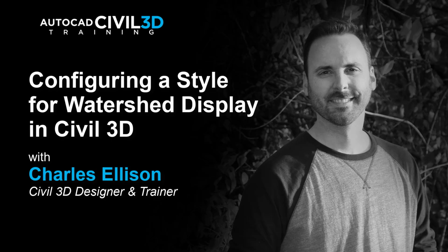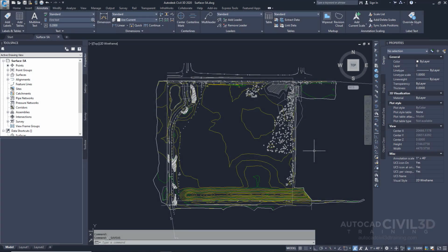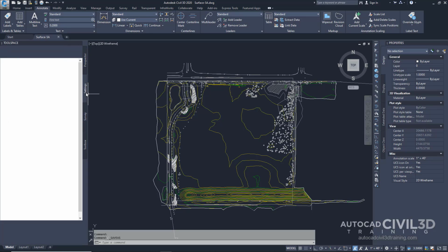In this tutorial, we'll be configuring a style for watershed display in Civil 3D. So let's get started. In this exercise, you will configure a style for watershed display. Go ahead and open up your Surface-5A drawing in your Tutorials folder. Go ahead and go over to your tool space and click on the Settings tab.